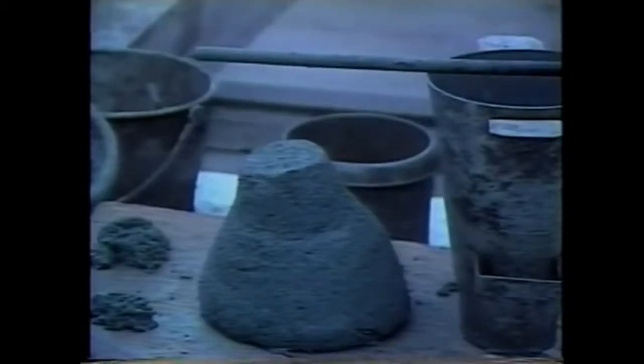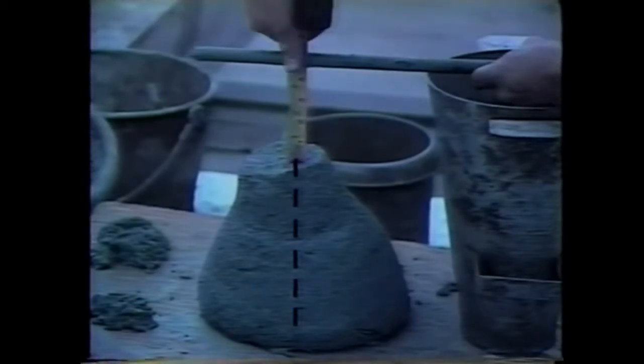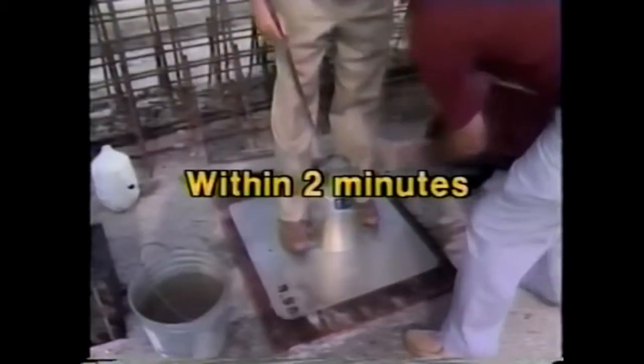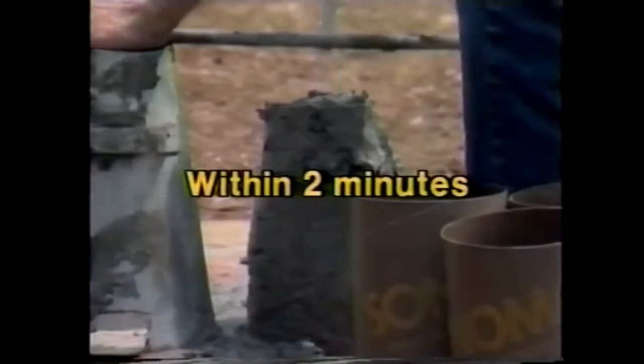The measurement should be made to a point that is directly above the center of the bottom of the concrete, not at the center of the top. The entire slump test must be accomplished within 2 minutes, as measured between the adding of the first layer and the measuring of the slump.